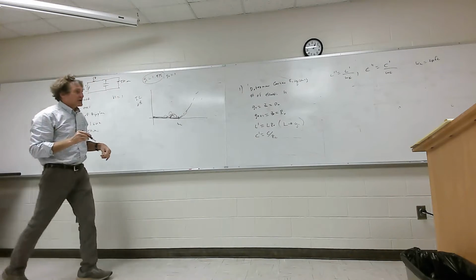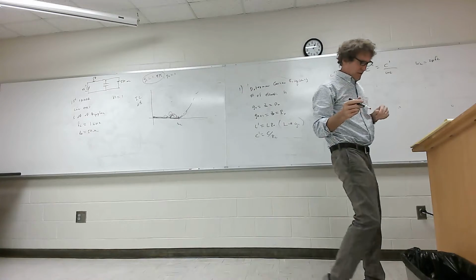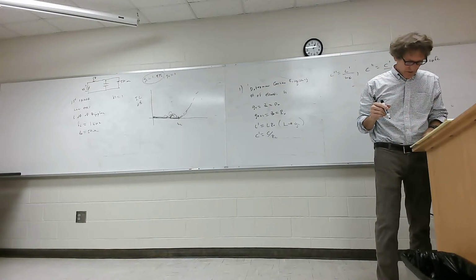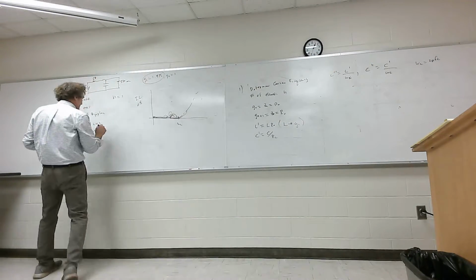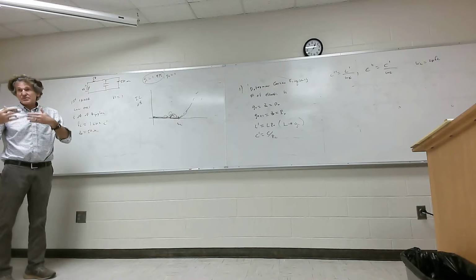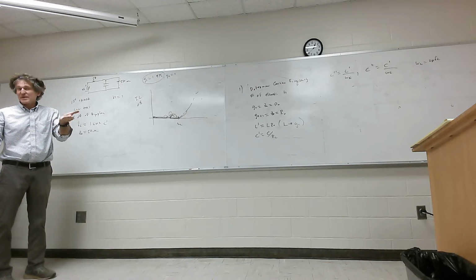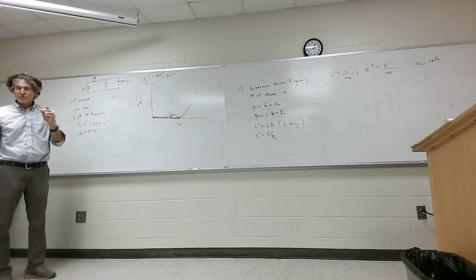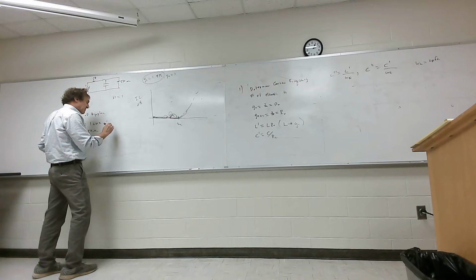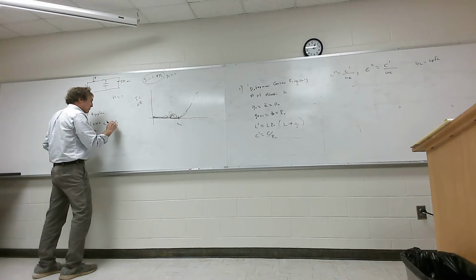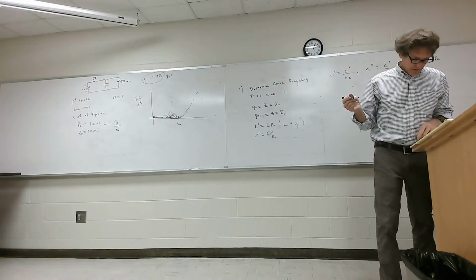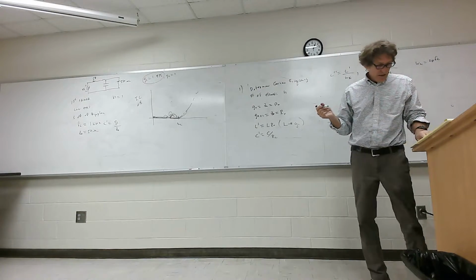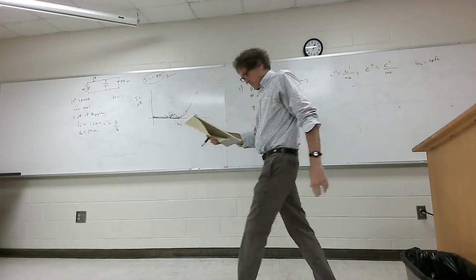Now, next you have to get the value of that capacitor if you want to use a capacitor for it. So for this one, you first get C prime. I'll put this here. This is an intermediate step. It's just the way it's done. I mean, we could go right to the final step, but he's showing you what's done in general. This is called normalization. So C prime is just going to be equal to this value of G1 divided by Z naught, I believe, he uses Z naught, and that comes out to be 39.9 millifarads.